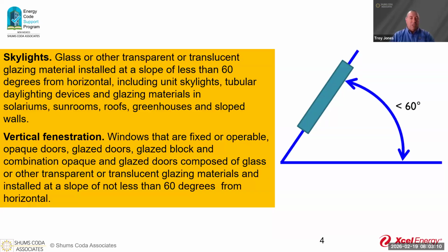So it seems redundant, but I always bring that up because I have had that question from some contractors in the past and a designer who was putting in a very, very dark stained glass window. So that did not transfer light through. We called it opaque, and therefore we're not required to have that daylight zone.